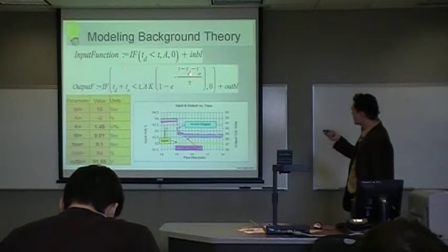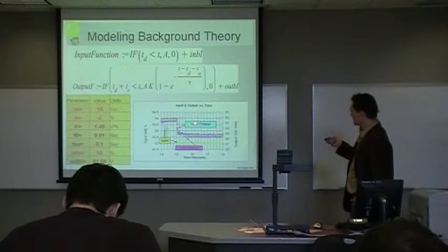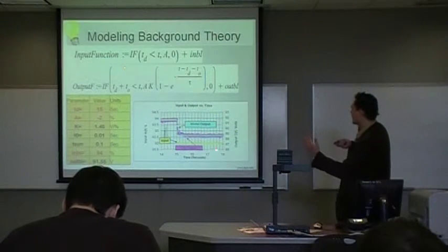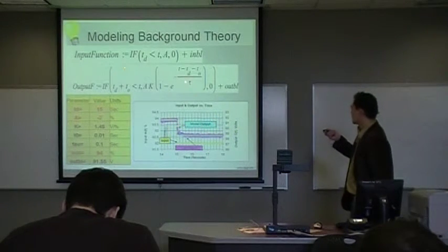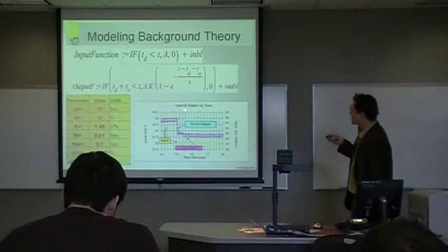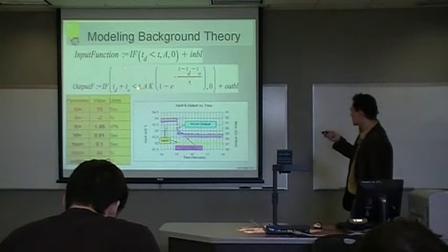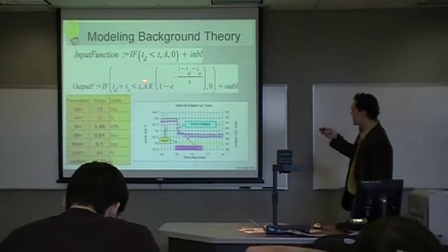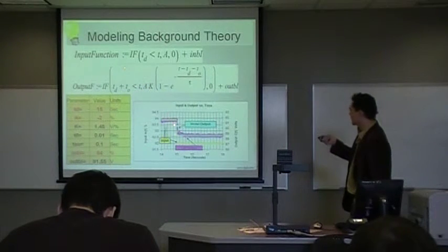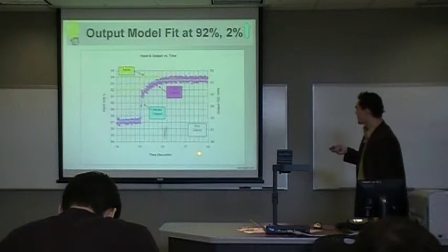And our tau on the bottom controls how wide the graph gets, so we had to adjust that to get it to match up. We modified that, and also A, of course, changes. In this case, our A was -2. That gives it whether it's going to be positive or negative. Our steps down match much better than our step ups.